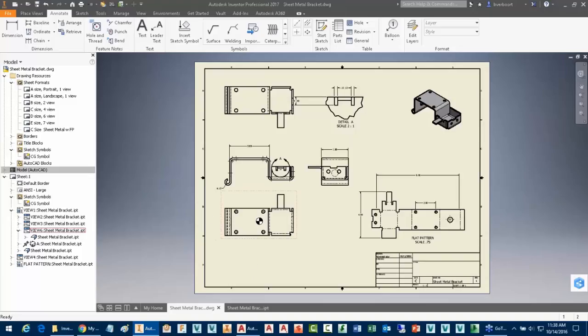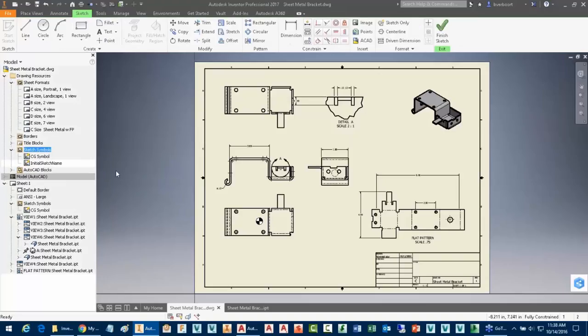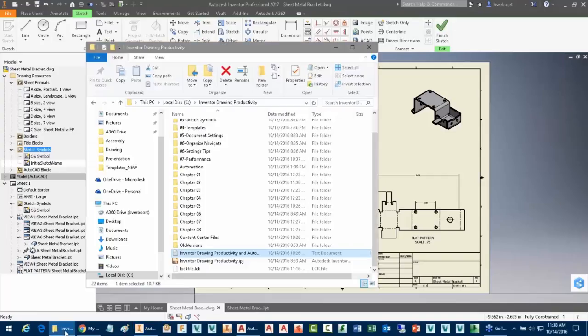You might try to include notes on the sheet itself, and then maybe you put a whole bunch of notes on there that's more than you want, and you delete the ones that aren't the notes you want to keep. But in this case, if we had a grouping of many different kinds of notes that are available to us and we could place them as a sketch symbol, then we could just pick what we wanted and put it in, and that's kind of the workflow I'm going to use here. So again, I'll go ahead and I'll just edit and create a new sketch symbol, so defining a new symbol here. And then I'm going to launch I've got a Word document here that I'll be using for this purpose.